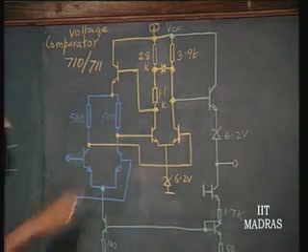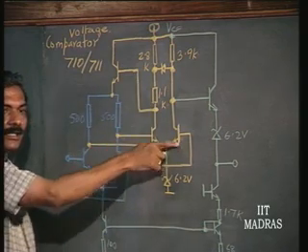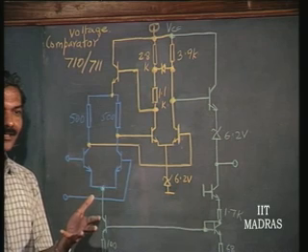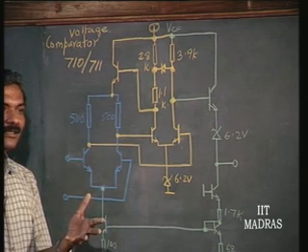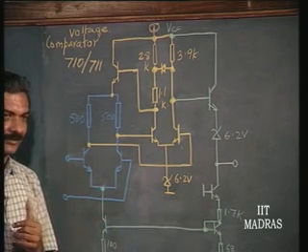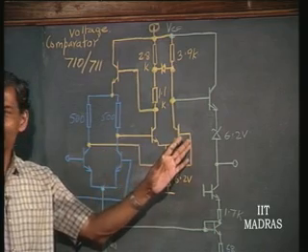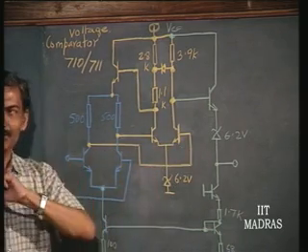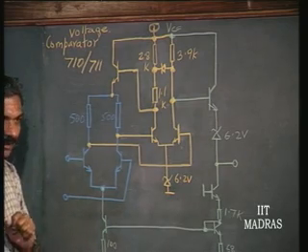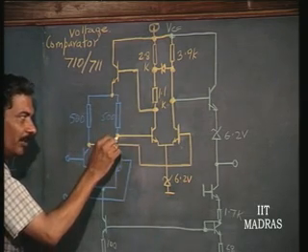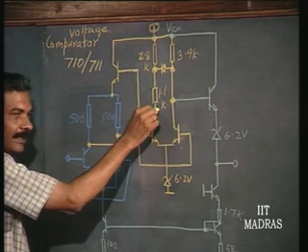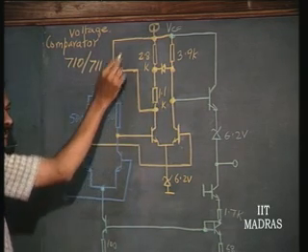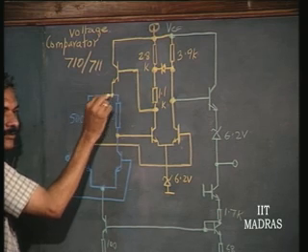and therefore these two are two independent amplifiers, okay. One is connected to one collector and another is connected to other collector, and therefore you are likely to lose gain by a factor of 2, because these are two independent stages, but I do not want to lose it. So, what is done is this output is getting amplified here, okay, and this output is sensed here by the common collector stage here and fed to this.